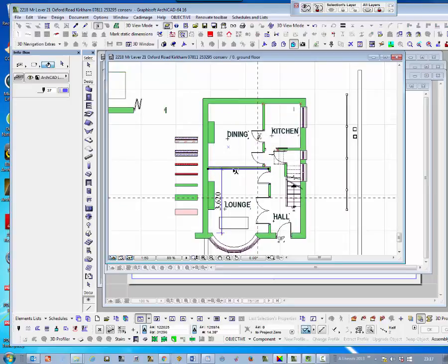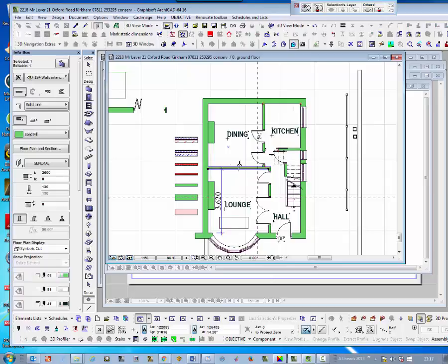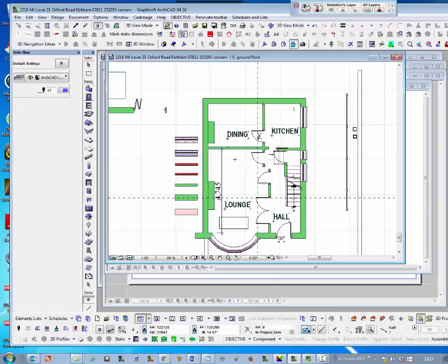Now then, what I can do is utilise the existing walls on the drawing, so I highlight that one by pressing shift and mouse button and Control D, and I pick it up by that edge and drag it to there. Okay. Now the width of this first room, which is the kitchen, is 3840.